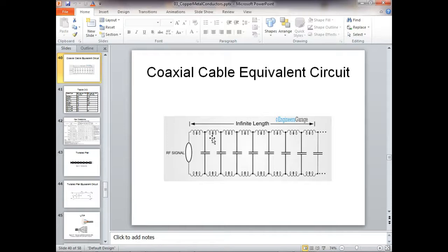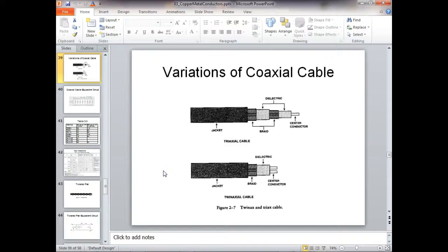You understand? So if I was to take an ohm meter on my coaxial cable and I was to measure from this wire right here out to the shield, it's going to measure an overload because you're trying to measure resistance, right? You understand that? Right? Everybody understand? If I was to measure from one end of the cable over to the other end of the cable, then I would measure the resistance of the wire, which is almost going to be nothing, right? You understand? But if I was to put AC on this sucker at a certain frequency, then it would have a certain impedance. And we call that the characteristic impedance.